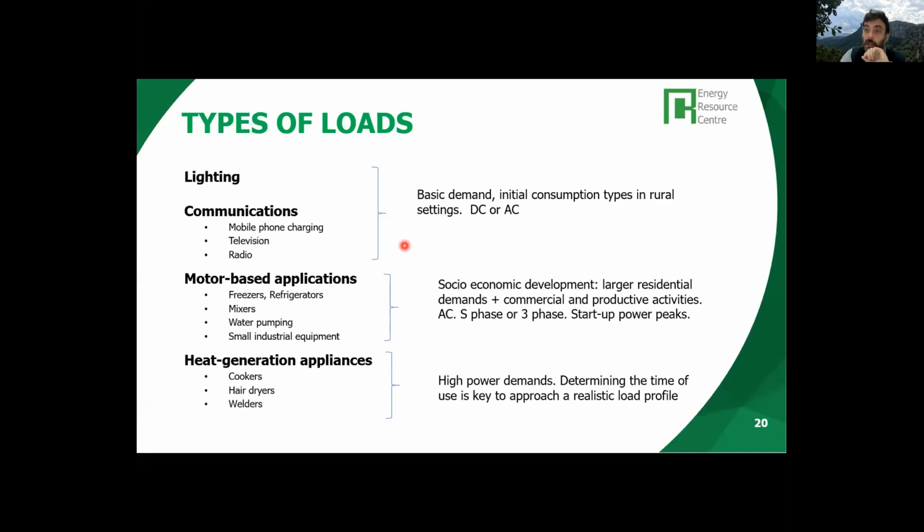What about the starting up power peaks of pumps and engines? We have very high peak currents at startup, which could last not even seconds, but milliseconds, yet it is a very important peak that the inverter will have to be able to cope with in order to supply that load. So the types of loads need to be understood and anticipated.